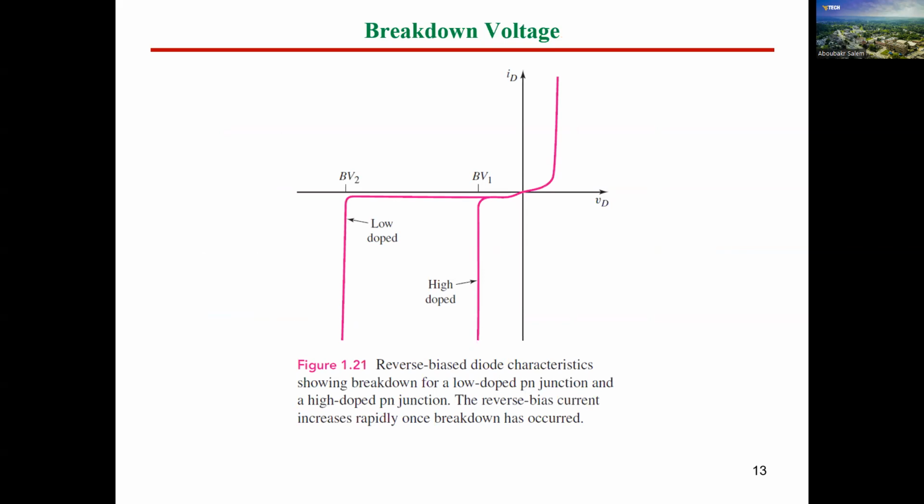So what is happening after reaching a certain level of volt? Actually, we have what's called the breakdown volt. What's the meaning of breakdown? Breakdown means the diode will be damaged. Why will the diode be damaged? Because the volt will be relatively high, and this volt will make a break in our junction. But it is breaking our junction, not just letting current flow, it's going to break it forever, which means the diode will be damaged if we reach this value. So we shouldn't operate the diode at this value.